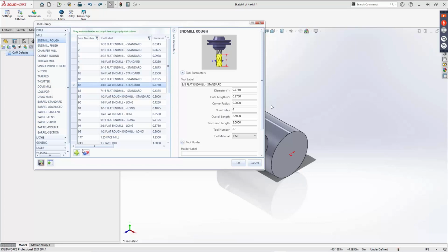So unfortunately, that's the issue with the tool library there. But if you do save it out and then save it, and if you do make any changes or add additional tools or whatever, constantly just resave on there. So you can do it. I don't recommend it. But if you do, just be sure to save a copy of it, because some things do happen.